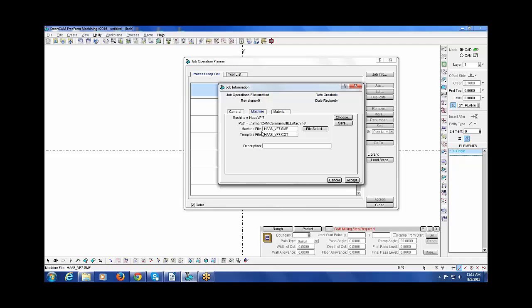So when you add a material here, it automatically creates a corresponding material file using a template file that we've provided. Whether or not you choose to make use of the material librarian speeds and feeds calculation capabilities, we've put the structure in place so that all you have to do is go back and edit that structure to get the speeds and feeds appropriate for the new material you've added.